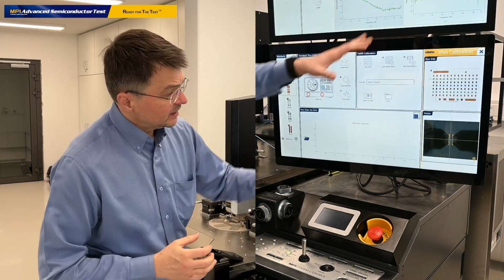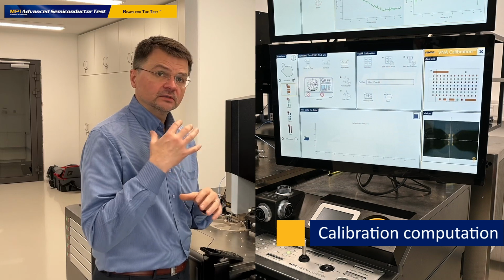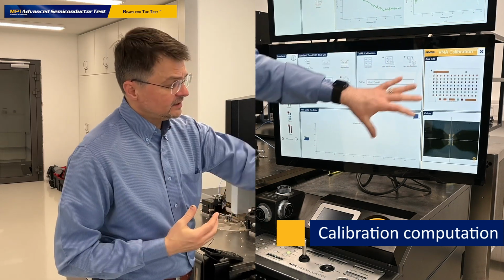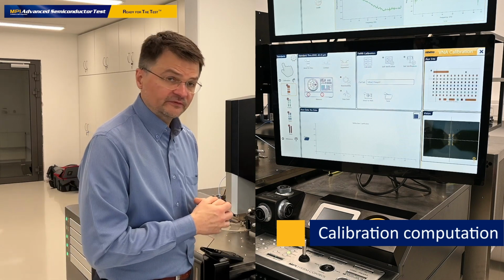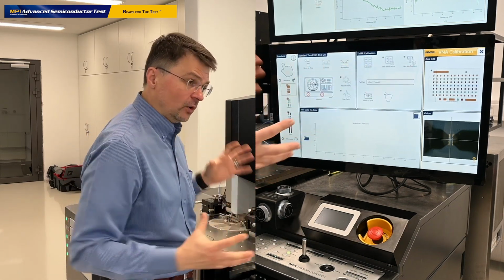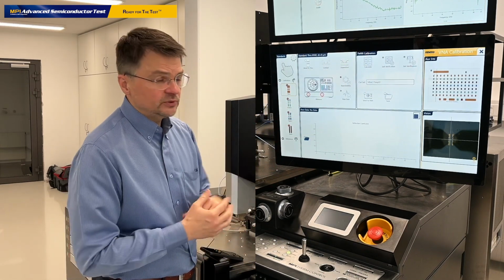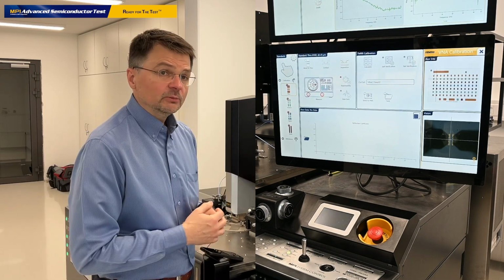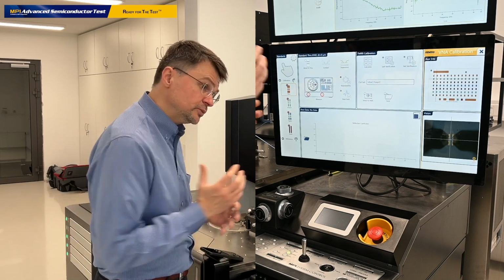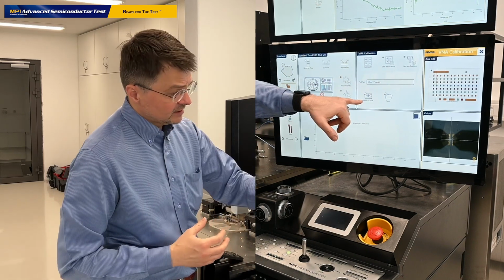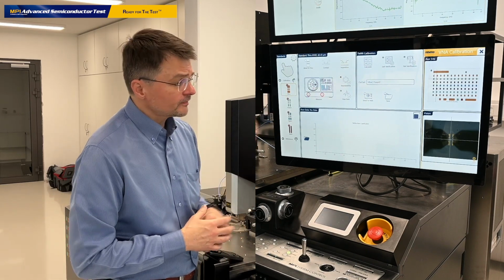So, the next widget controls the calibration computation. That is currently the widget which is configured for through match reflect. From this widget, once all the data are collected, we can compute error terms. We can define the name of the error set, and after the error set name is defined and error terms are computed, we push them to the network analyzer memory by send to the VNA.